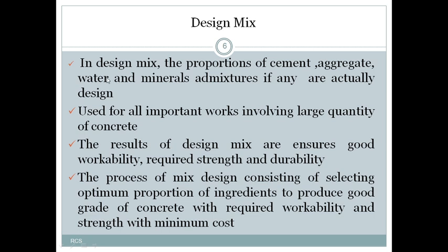Because of the accuracy of this design mix, we can use it for all important works where a large quantity of concrete is required. The result of design mix ensures that it will give good workability and the required strength and durability. The whole process of mix design consists of selecting optimum proportions of the ingredients of concrete, like cement, aggregate, water, or mineral admixtures, to produce a good grade of concrete with required workability and required strength with a minimum cost. That is the motto of designing the mix.